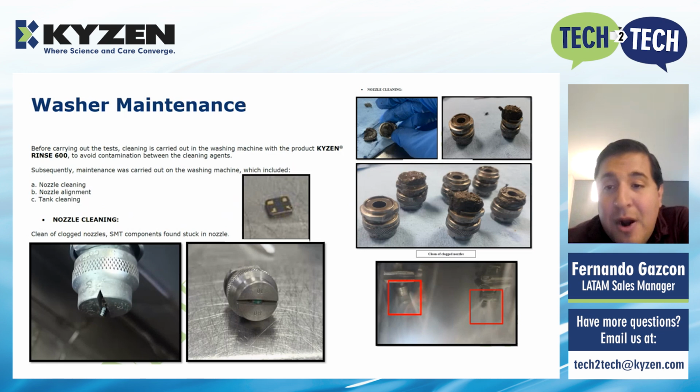While checking the spray bars and nozzles, we noticed many of them were clogged with different soils and residues, from mud-type residues to Teflon tape remains, or even small electronic components that made their way up to the spray bars through the pump. This was an important problem for their cleaning process because they rely on the washing equipment being able to deliver the cleaning solution onto the board surface with the appropriate flow and pressure in order to achieve the cleanliness levels they were looking for.